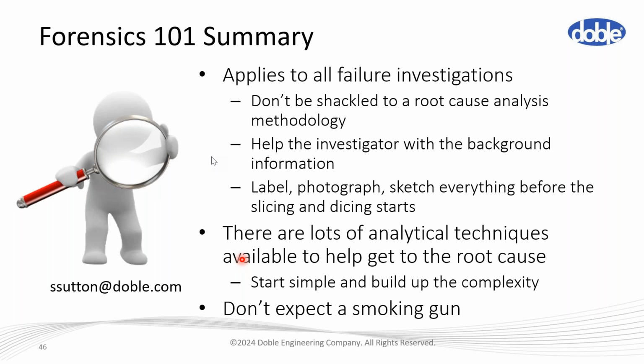But to be able to predict failures or prevent them, you have to know what the failure mechanism is. So if we have a medium voltage cable that could fail through water treeing, VLF tan delta is a really good tool.